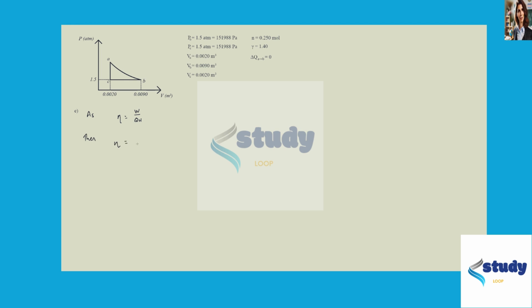So the efficiency is equal to 1,758 joules, which we worked out in part D, divided by 5,482 joules. And this gives 0.32, which when times by 100, gives you 32%.